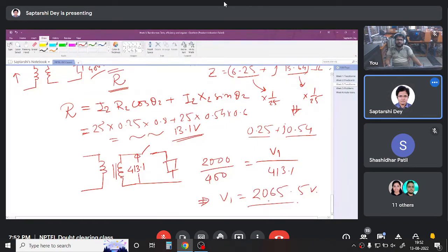So what happened here? We applied a voltage more than the rated. So we got a voltage in the secondary also more than rated. And this extra voltage was such that on load, it came out to be the rated voltage. But that doesn't mean that voltage regulation is not happening. It is happening. The primary voltage is more than rated. Is the question clear? This is a little bit of a tricky question to trick the students. That 400 volt is the rated voltage, 400 volt we are getting, so zero regulation. No. In a practical transformer with lagging load, you can never have zero regulation.